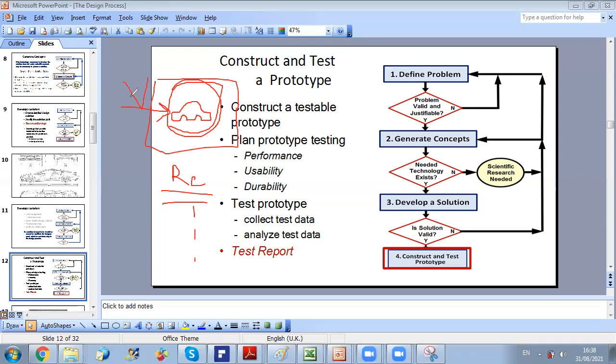In reality, it's air, but you can use water in the experiment, for example. The only condition is to have similarity. So if you remember the chapter on similarity and dimensionless groups in fluid mechanics, this is its application here. You can apply it in your design process. Whenever you determine the dimensions I can take for my prototype and the conditions in my wind tunnel experiment that are similar to the real case scenario, then you can construct your prototype and perform several tests and experiments on it before producing your final car.